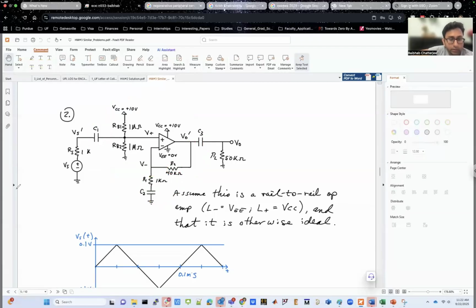So let me clear this out to make this point a little better. What is the DC voltage at this point if you do not have this capacitor? If you do not have this capacitor and let's say the bottom terminal of the R1 resistance is directly connected to ground, in that case, there is a DC potential here. There could also be a DC potential here. The DC potential of this point will be 0 because it is connected to ground.